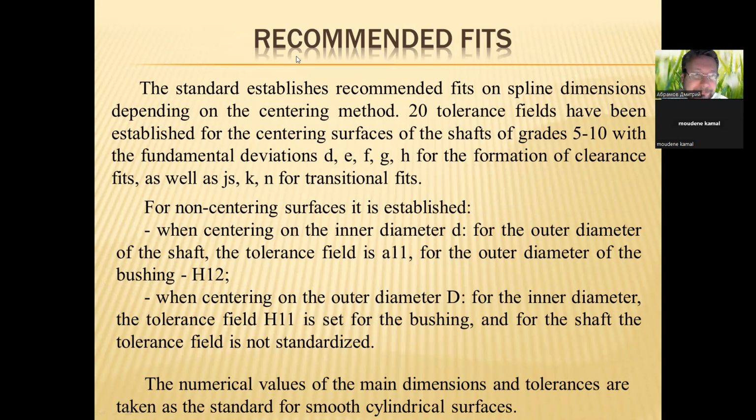Recommended fits in splined joints. The standard establishes recommended fits on spline dimensions depending on the centering method. 20 tolerance fields have been established for the centering surfaces of the shafts of grades from 5 to 10 with the fundamental deviations d, e, f, g, h for the formation of clearance fits, as well as js, k, n for transitional fits.